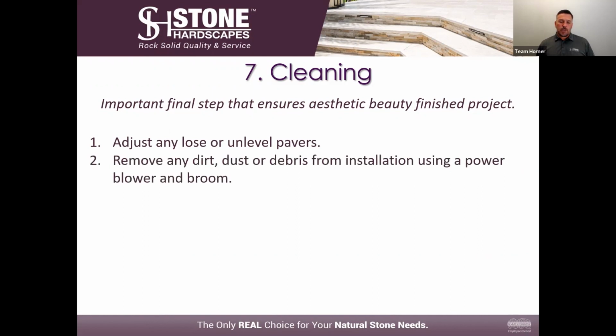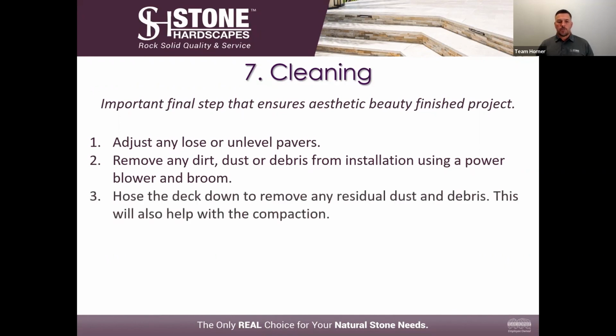First step of this is you're going to want to remove any of the dirt or the dust or debris from the installation using a power blower or a broom, keeping in mind that you don't want to blow it into a finished pool, or into the house. But this gives you the ability to get rid of all of that. During the installation, if you're cutting a lot of pavers, there's going to be a lot of dust on your paver. You want to remove it first.